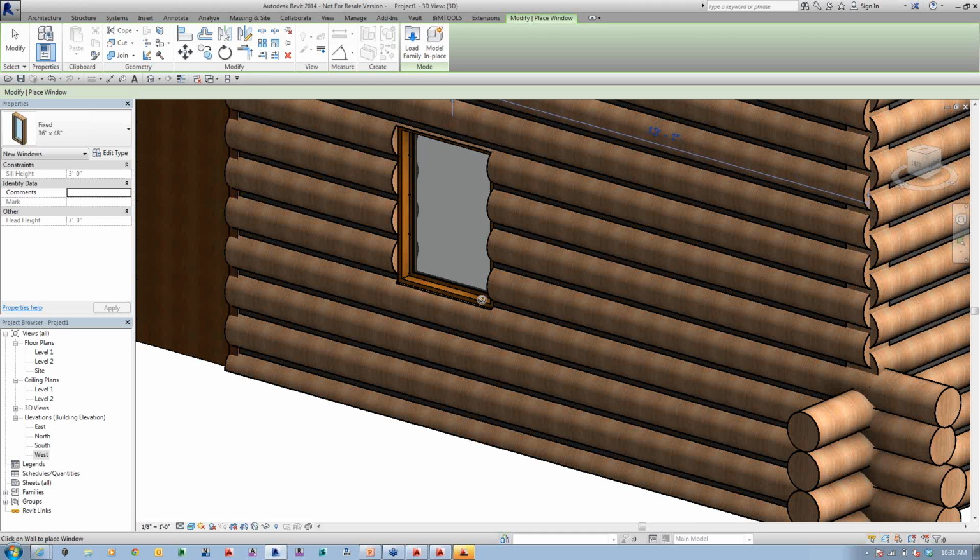One of the weird things we have with windows is that you cannot do any negative space from them. You can create solids but no void forms with a window, which plays some nasty tricks. So if you really wanted something beveled at the sides, at the top, at the bottom with the door and the window, you're going to have to make a separate void form. I just kind of said, forget it. I'm not in the business. Maybe on a bigger log home, something in the neighborhood of 7,000-8,000 square feet, not a small cabin, I might take the time to do that.